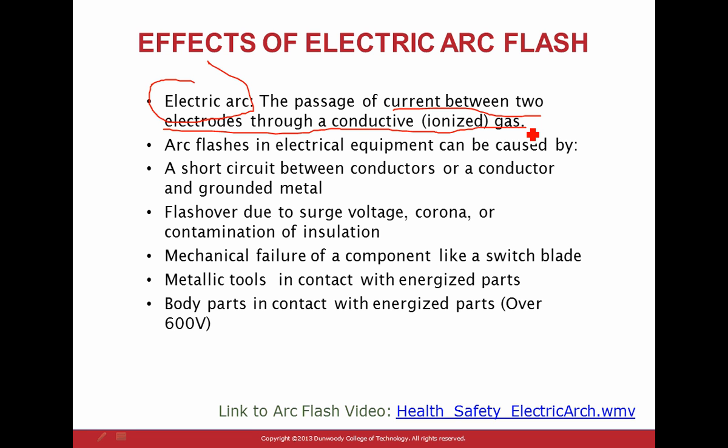So what kind of flashes are there? The backhoe rips up a 1.5 kilovolt line, or 3 kilovolts. It was a big ball of fire, but it's not a short circuit. A proper short circuit is bolted. A bolted short circuit, you touch them. Anything that has an impedance on it will create an arc flash. You will see a big ball of fire coming out of it.